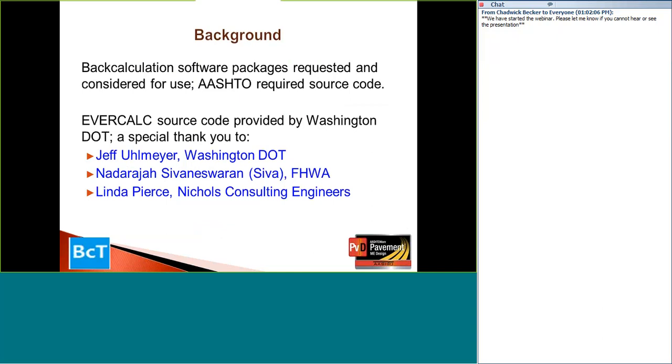One of the requirements for using different back calculation programs, however, was that AASHTO wanted a copy of the source code to ensure that it could be maintained and updated along with pavement ME over time. The only program that provided its source code to the AASHTO Pavement ME Task Force group was EverCalc.